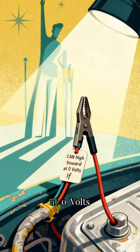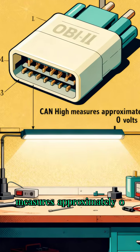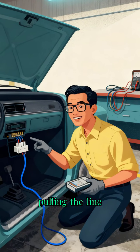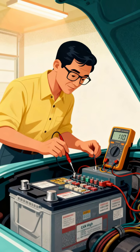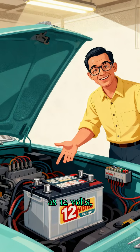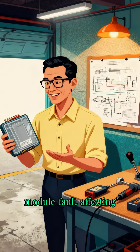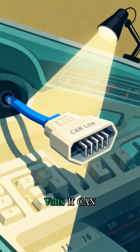CAN high toward 0 volts. If CAN high measures approximately 0 volts, it may indicate a short to ground, or a failed control module pulling the line low. CAN high near battery voltage. If CAN high measures close to battery voltage, such as 12 volts, suspect a short to battery voltage, wiring damage, or a module fault affecting the network.